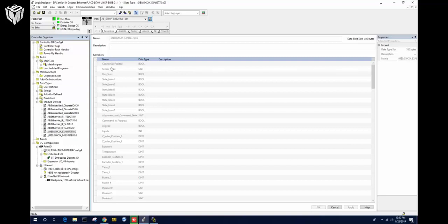So all of the information is not only named, but of the proper data type, except for 64-bit values. Studio 5000 versions 31 and older will not support 64-bit values outside of the copy function. Version 32 and newer will support 64-bit values in specific function blocks, so you should pay attention to that. This will affect pieces of data like our encoder position, which you can see gets split up into two DINT values, our encoder index position, time, and the current frame.